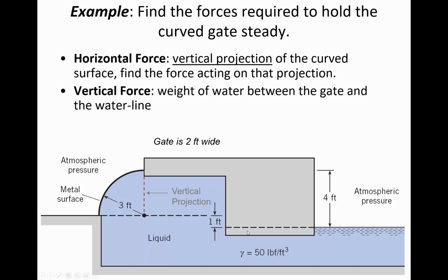That means that now the pressure is becoming negative in terms of gauge, not in absolute terms. Here at the interface of the air and the water, the absolute pressure would be 101,325 newtons per square meter. But in gauge pressure, it's zero. So in other words, as we're going up through the fluid, the pressure is decreasing. And so that's going to suck the gate in towards the liquid. Instead of the water pushing out on the gate, since it's a negative pressure above the water line, it's pulling the gate down towards the bottom.